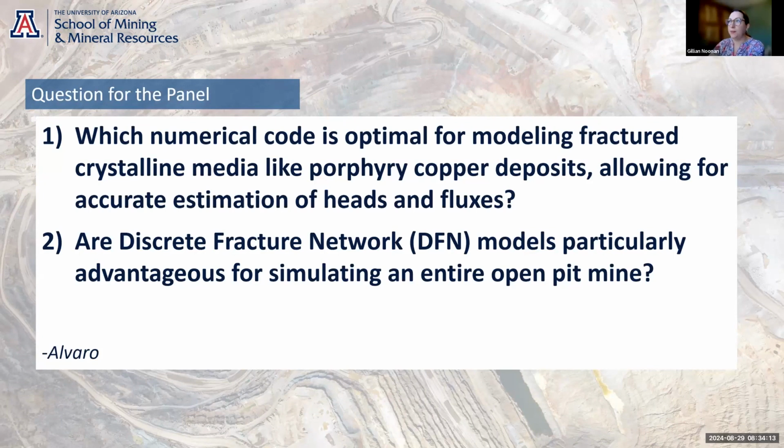Travis, did you have something to add? DFN again, the same thing. A lot of fracture systems have no hydraulic conductivity whatsoever. They're clay filled, or they're mineralized, or there are large stresses that render them closed, and so the DFN in and of itself doesn't help with the hydrogeology. It's understanding which of the fractures are important to groundwater flow, and that requires a lot of data and site understanding. So DFNs generally aren't used for monitoring or modeling groundwater flow and pore pressures in open pits.